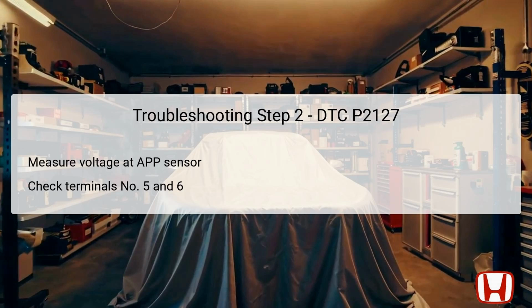A reading of about 5 volts indicates that the supply voltage provided to the sensor is adequate. If the voltage is present at this level, the troubleshooting can continue by moving on to further steps in the diagnostic process.